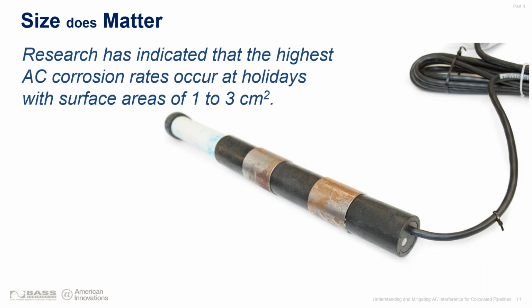Let's talk a little bit more about the coupons. So there's a variety of coupons out there in a variety of different sizes. Pictured here is the Triton triple coupon that we have. So it has 3 coupons. Those 2 larger ones, those 2 metal pieces that you see there, are going to be for checking the effectiveness of your cathodic protection system. So one of them is designed to be connected to your cathodic protection. The other one is supposed to be your native coupon.